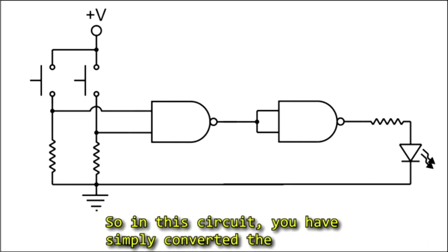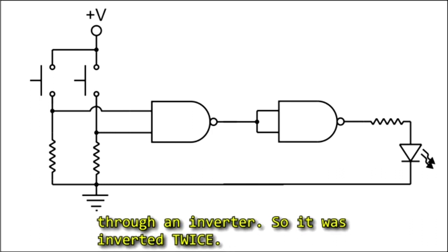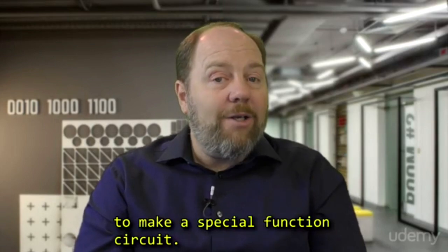So in this circuit, you have simply converted the NAND gate into an AND gate by running the output through an inverter. So it was inverted twice. So go ahead and build those circuits and play with them a bit. In the next lesson, we'll use this chip to make a special function circuit.